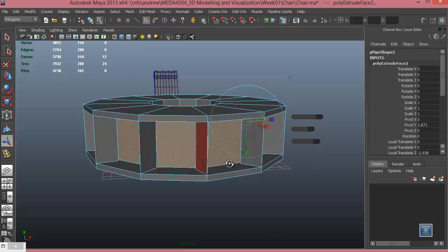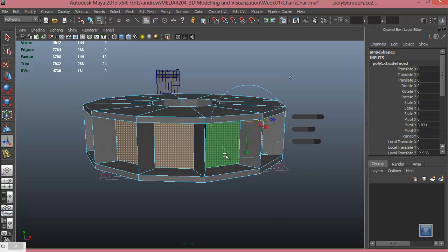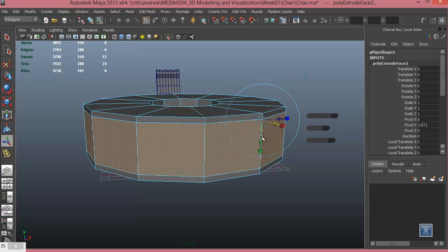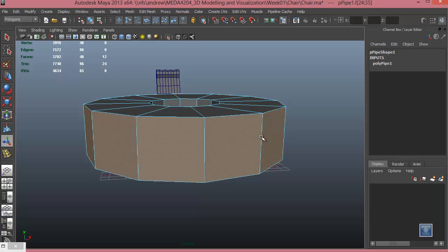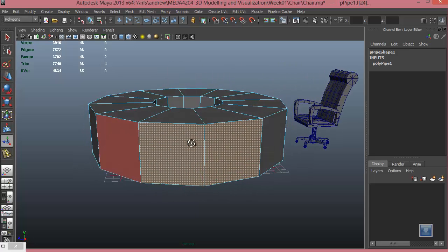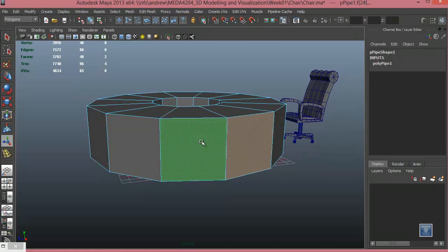faces together. Now if you get into this kind of problems, it is always better, instead of just pulling it back to its original place, you can simply undo. So I'll go ahead and do that. Control Z once, Control Z twice, thrice, and one more time. Make sure that you do undo until you leave the selection, because if you leave an extrude in the same place, it would create lots of problems later. So undo until you lose the selection, and now we can select it again,